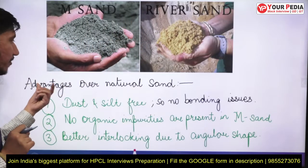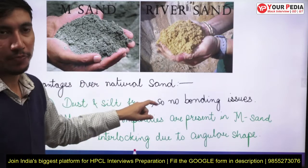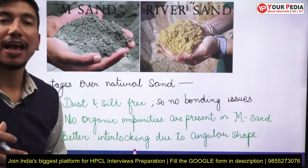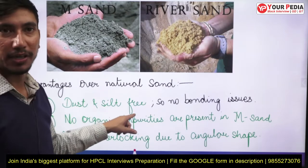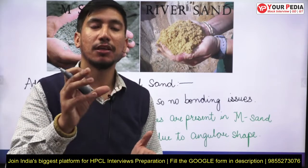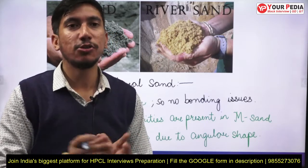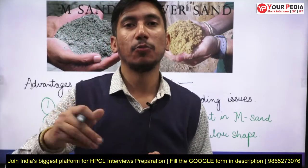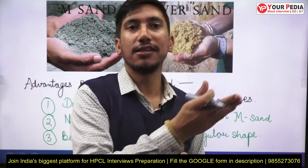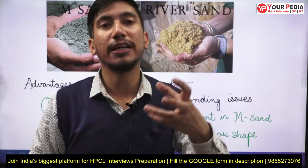So now coming on to the advantages of M sand over natural sand. What are the advantages of M sand? The first advantage is that since it has been well washed and well graded, there is no dust or silt present in it. Moreover, there are no organic impurities present in it, because here we are taking granite stones only and crushing them into smaller grains, so there is no organic material present. What happens in natural sand is that some organic impurities get mixed in while the sand is being transported, so we don't want those impurities, because they will create problems.